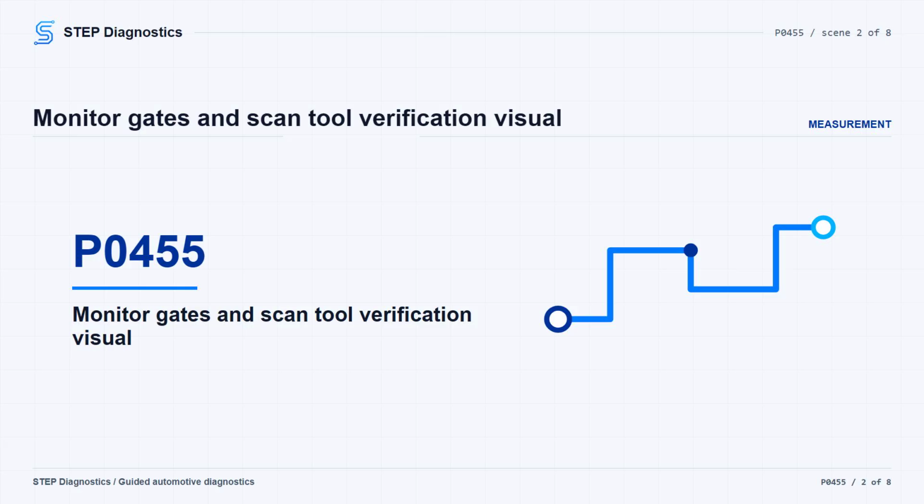Next, turn the ignition on, run the small leak verification test with the scan tool, follow the screen prompts, and document each phase result. If the routine passes, the system may be sealed at that moment. Compare the data to the manual phase expectations, and if it is functioning properly, do not make a repair attempt. If it fails, or if the routine is not available or will not run, move into the manual EVAP evaluation.